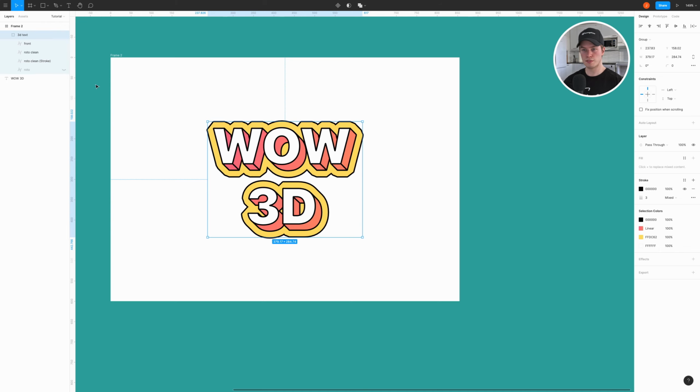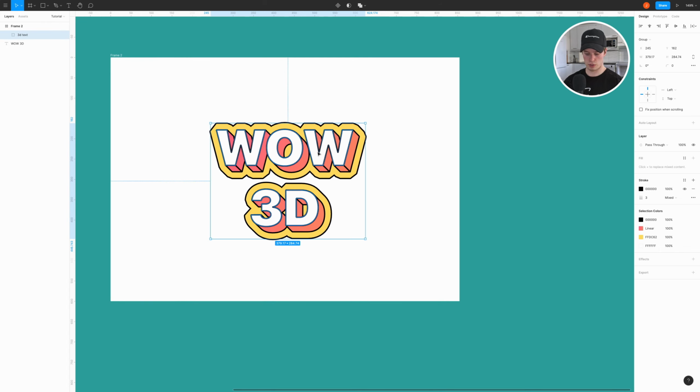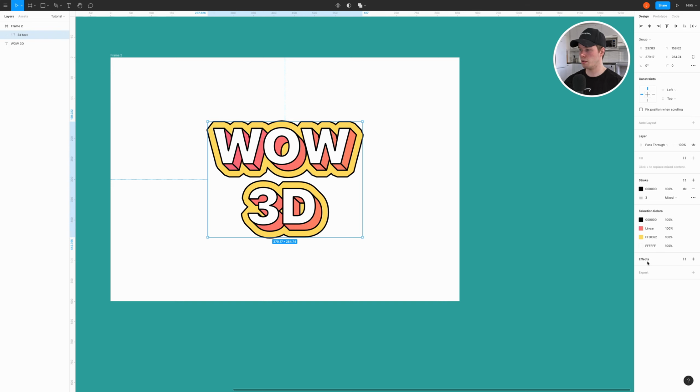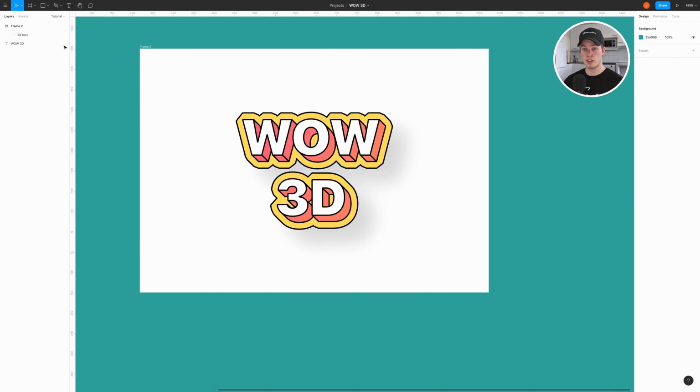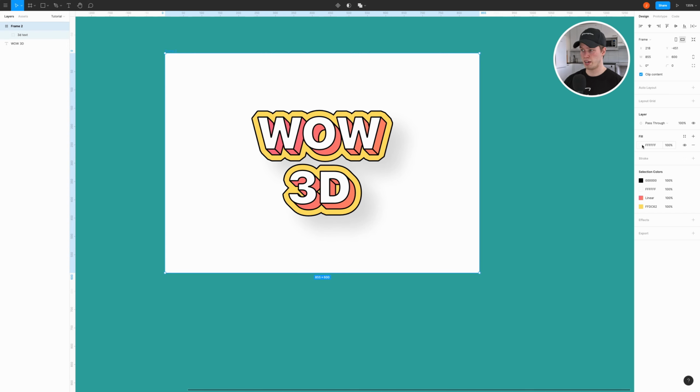And now we can finally add some color to the background. Or actually, let's first make this pop a little bit by adding a drop shadow with a really large blur. Like, let's do 50. And let's play around a little bit with positioning. Do something like this, I guess, and then tone the effect down a little bit. 15% is okay.